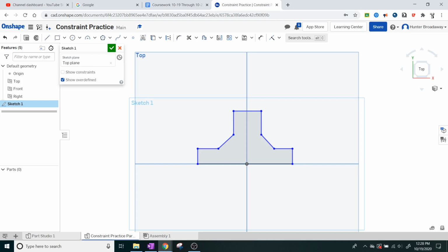Let's see here. Investigate how the constraints affect sketch behavior by selecting individual lines and points and dragging each using your mouse. Okay, so what you can do is see how these constraints relate to each other. You can click on individual parts of the lines and move them around. And since some parts are constrained to each other, like for example, these are the perpendicular constraint, if we were to extend these two lines out, they would be at a right angle to each other.